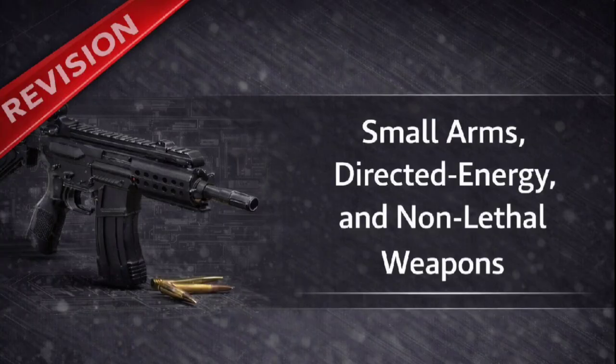It's capable of accurate engagement at 1,200 meters. This distance demands a system that eliminates almost all variables, which leads to the use of a manual bolt-action mechanism. The reliance on manual bolt action is the fundamental technical reason for its superior accuracy at these extreme ranges, especially using powerful ammunition like the .338 Lapua Magnum. Because automation introduces variables. Exactly. Moving pistons, unlocking lugs, they all introduce tiny inconsistencies. A manual bolt action removes them.